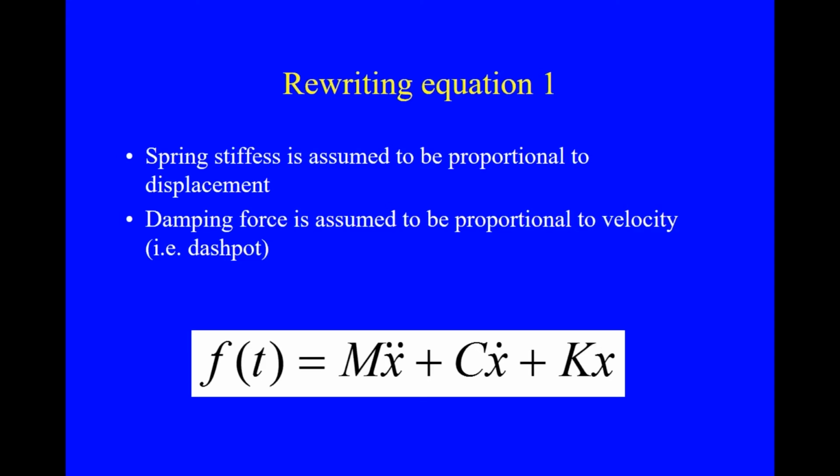What we've done is to put a completely different model to damping, work it through, and re-arrive at the concept of equivalent viscous damping. But now, we're not putting car dampers into our buildings. What we are doing is assuming that the major contributor to energy dissipation, that's damping, is friction.